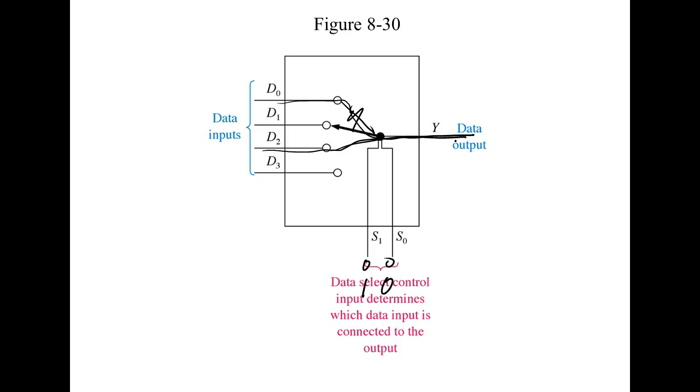So what's the advantage of multiplexing? Media, right? It allows you to have 200 and some channels coming in on one cable. It allows all of us to be talking on our cell phone at the same time, because we're multiplexing. Now, all those are broadband, or frequency domain multiplexing. What we do on baseband is we save conductors.